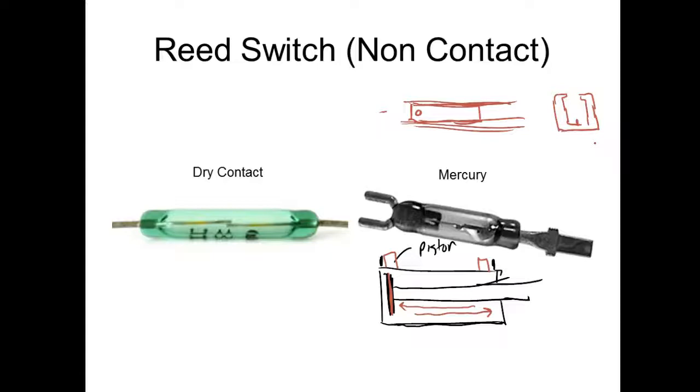Little tiny things. What they'll do, though, is normally they'll put a light emitting diode in series with the switch. And these guys here don't drop very much voltage, like 1.5 volts. But good gracious, we're operating on 24 volts. So dropping 1.5 volts is basically nothing, right? You understand that? And what this means is, now it'll give you an indication of whether the reed switch is made or the reed switch is not made.